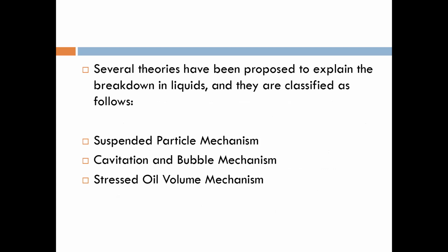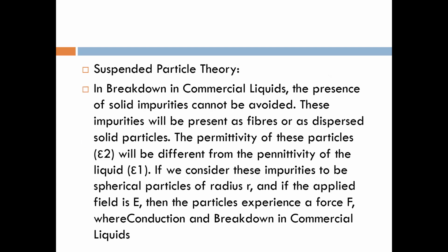Now, in practice, there are several theories proposed to explain the breakdown in the liquid. But the three main important ones are the suspended particle theory, the cavitation and bubble mechanism, and the trace oil volume mechanism. These three theories explain the breakdown in the liquid. One by one we will see them.